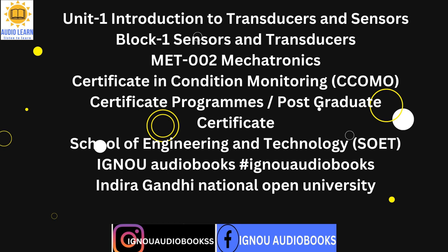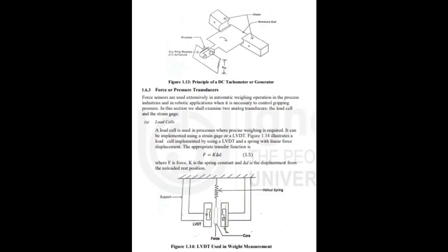A. Optical encoders. Since velocity is the positional change with respect to time, any positional transducer can be used to measure velocity. If θ1 and θ2 are two sequential angular positions of the encoder given in radians, then ω is equal to (θ2 − θ1)/t (1.9), where ω is the instantaneous angular velocity in radians per second and t is the increment of time between sequential position changes. B. Tachometers.